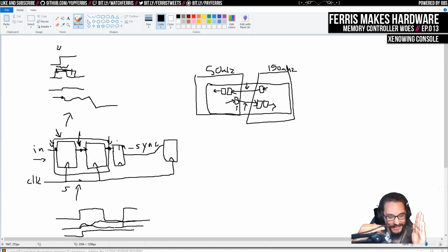And on the other end, if it didn't capture that change because of the metastability issue, you either get the previous value or the next one, and both are safe to assume, because of the way a FIFO works. If you're being sort of pessimistic, then if you have the previous value, then you're still safe if you don't have quite the updated value. So the consequence of not knowing that someone just wrote to the FIFO is that you still assume it's empty, so your FIFO is safe.